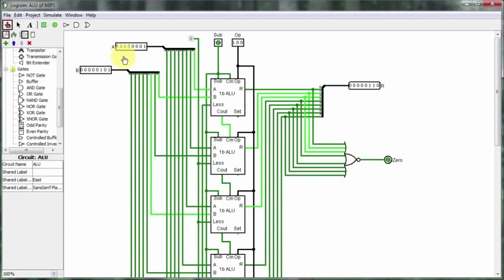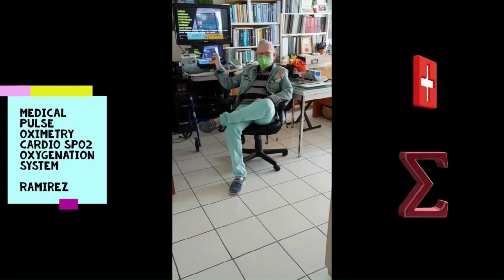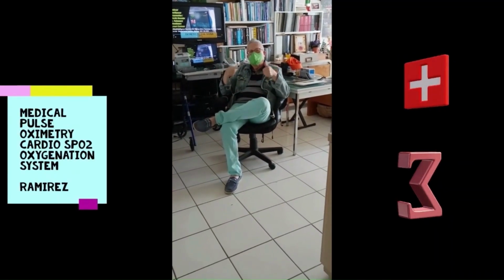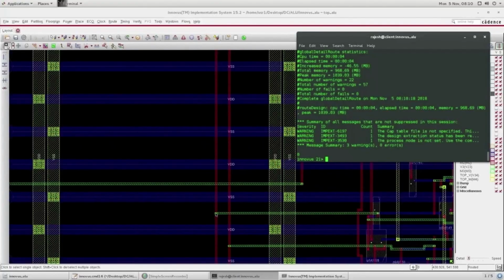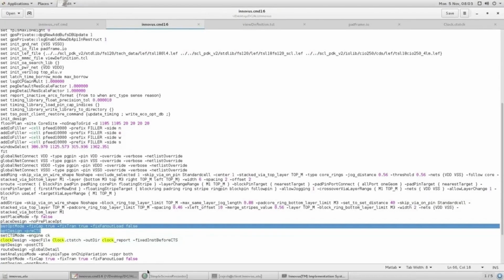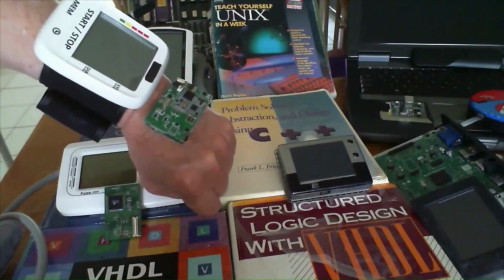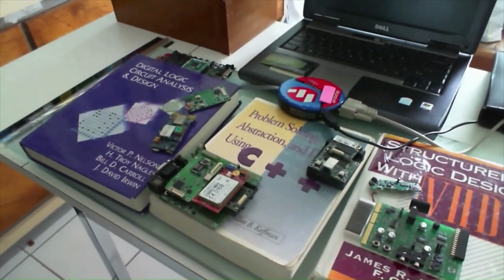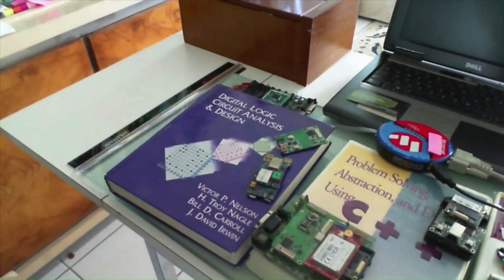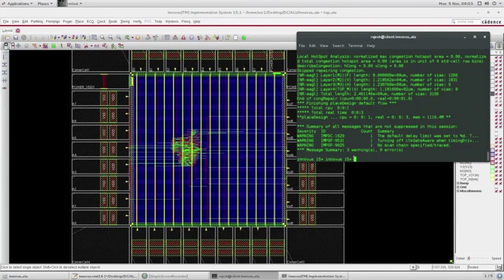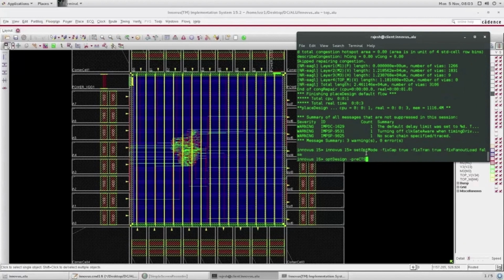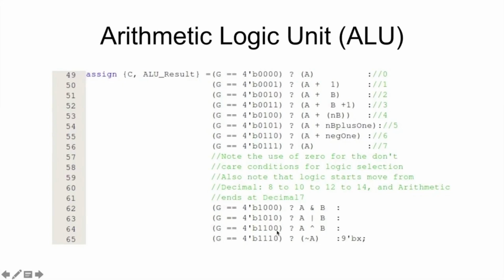Both clock optimization and power optimization can introduce overlap. This overlap can simply be removed through a brute force technique, or overlap removal can be performed with some of the placement optimization. It is important to ensure that the quality of the placement is maintained, such as clock skew, timing, and wireability. For instance, the smallest clock skew is achieved by preventing the circuits in timing critical clock trees from moving during overlap removal.